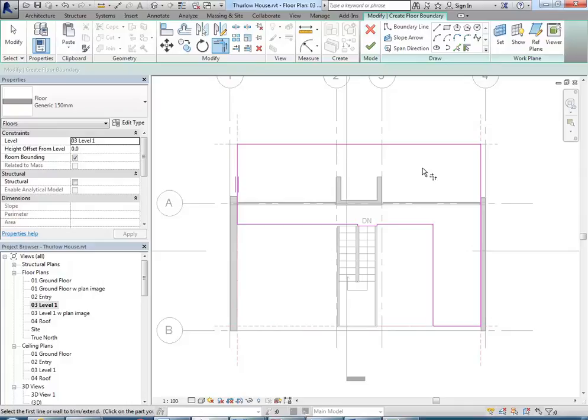Well, no, because you've never used pick walls to pick that side already. So you can just join the line that you made using pick walls. So using trim, the corner. Yeah, that's it. And then choose the wall on the side. And then on the side you've got a line, so click there, right? And then same on the left, in the top. And then also join that line to the bottom, to the wall. No, to the one next to the railing.